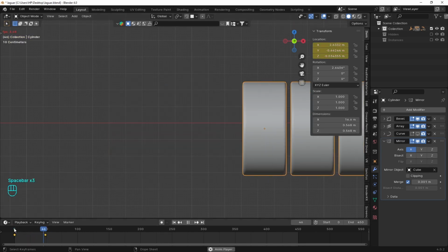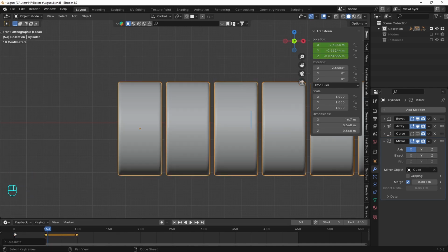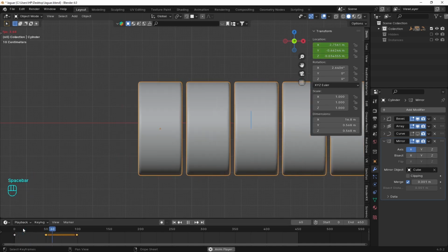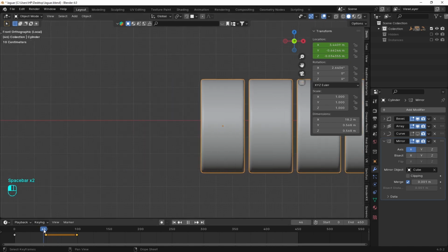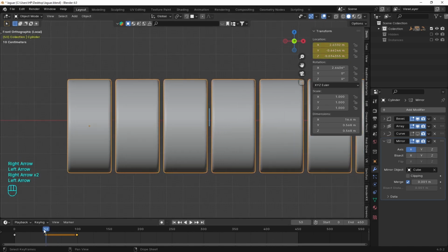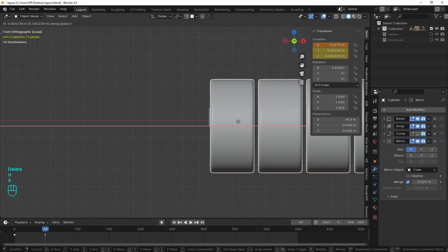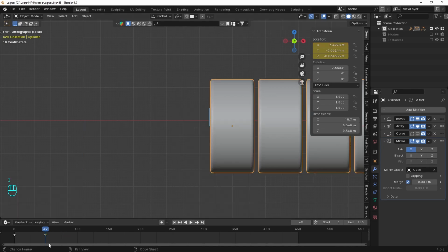The trick is to make it look like the last keyframe is 1 frame before the first keyframe. If it doesn't run smoothly, we can always delete keyframes and tweak the first 2.